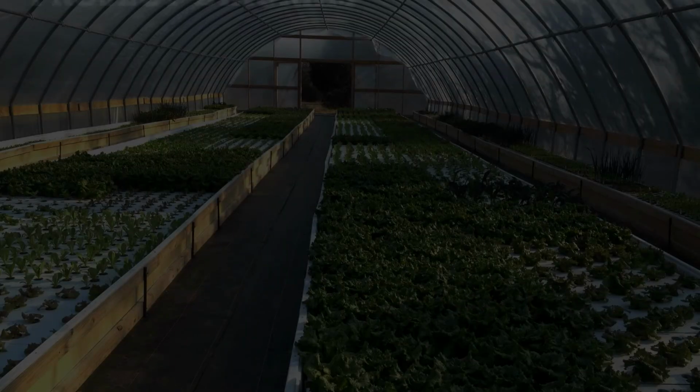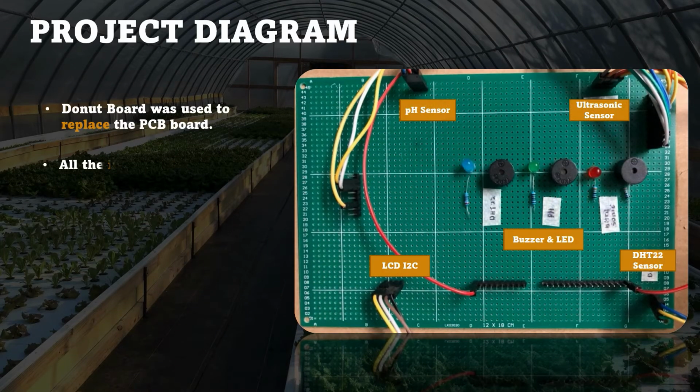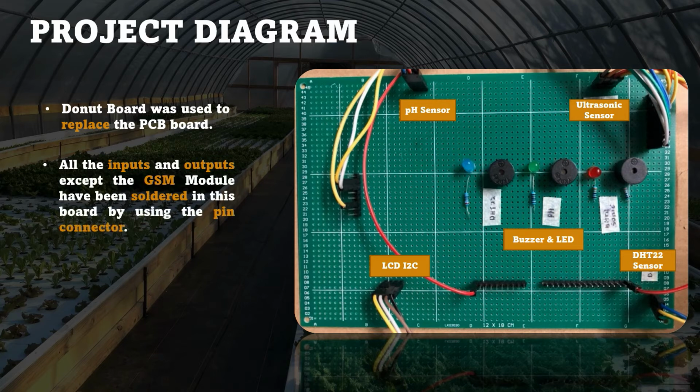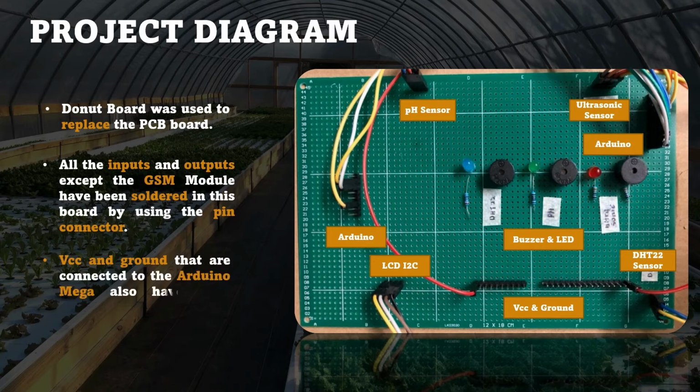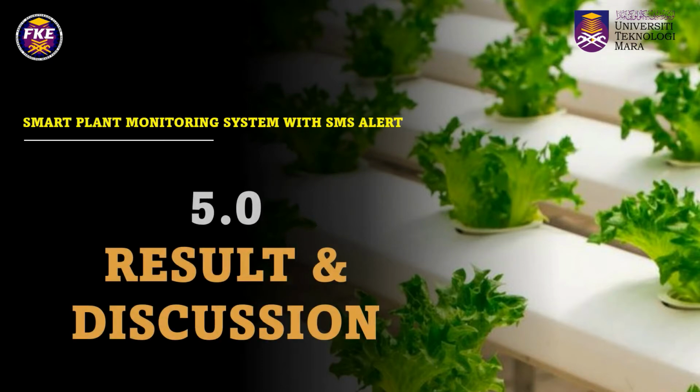For the project diagram, the donut board was used to replace the PCB board, and all the inputs and outputs except the GSM module have been soldered on this board by using the pin connector. Other than that, the VCC and ground that are connected to the Arduino Mega have also been soldered on this board. The fifth subchapter is result and discussion.